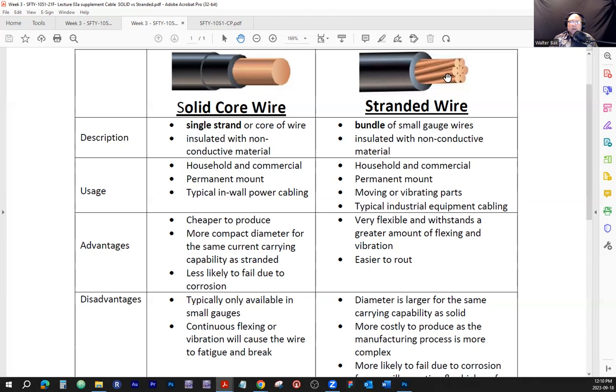Over here, in total, way more area is exposed, because each single strand is exposed, so it's almost like cut through, and it's kind of in stripes. So way more of the copper is exposed by volume to the elements. So this will corrode quicker than that.